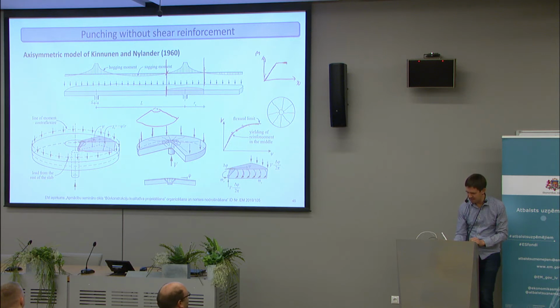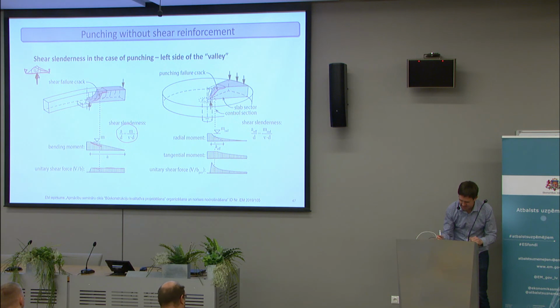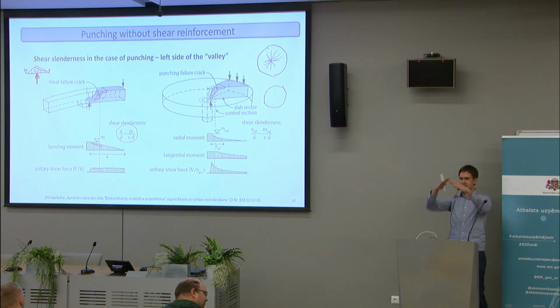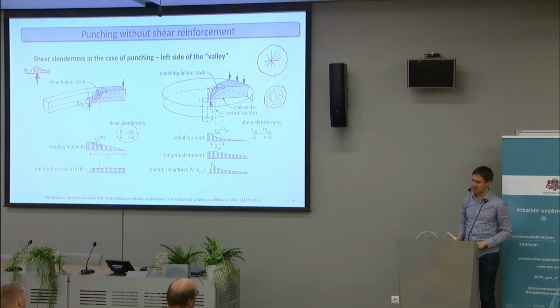In the middle, in here, you have a part that is cracked in both directions, and then in here you have cracks in this direction, because there is radial moment, which is basically for the reinforcement that would be placed like this. And then there is tangential moment, because if it's cone-shaped, then there is also curvature in the tangential direction. So we would need to put reinforcement that is round like this. That's against the tangential moment.